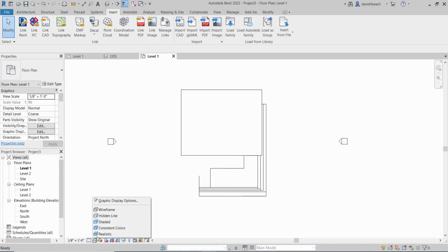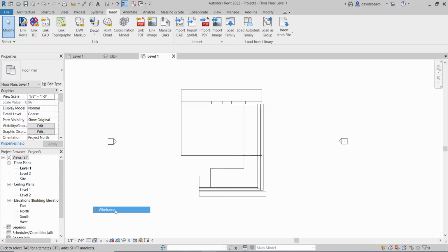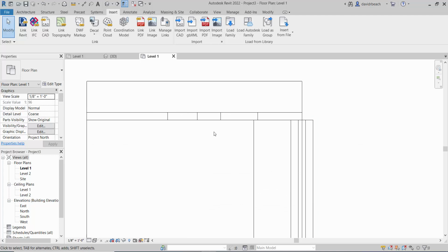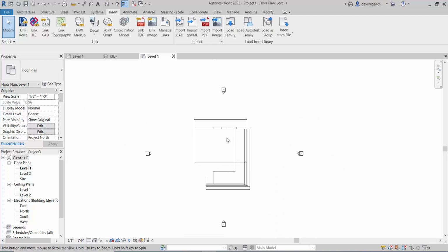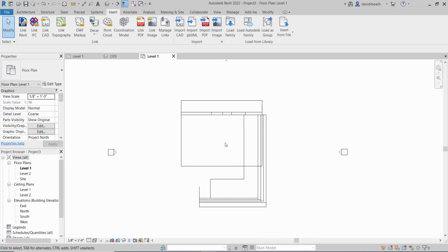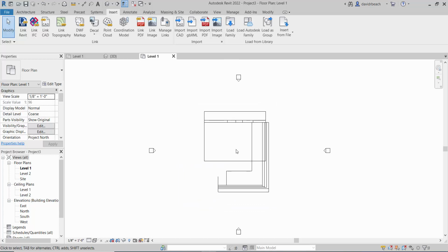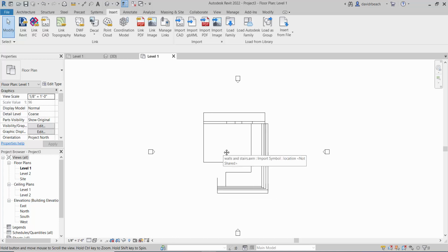But the quick solution around that, to be able to sort of see the guts where the doors and windows are, is simply to set it to wireframe. And as long as your object isn't too complicated, setting it to wireframe is going to allow you to see this, to be able to print it out, use it as an underlay, and continue moving the design forward.